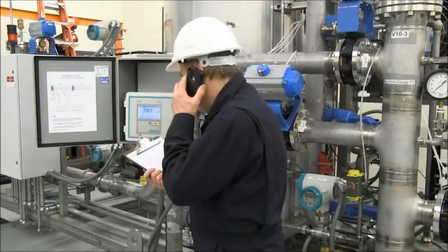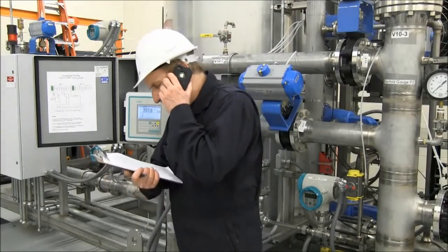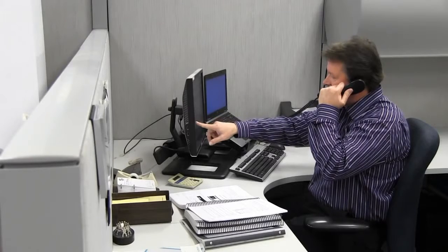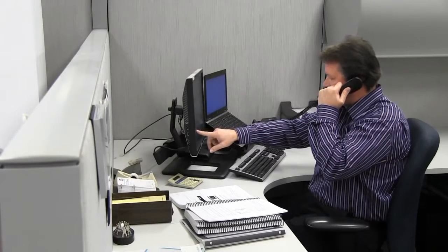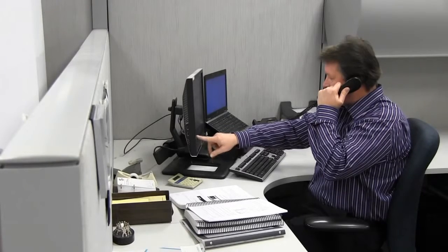Optimization is an exercise of collecting density and viscosity data for your actual liquids and matching them to the liquid table. When the values do not agree, an adjustment to the liquid table is made, which can be thought of as an in situ calibration. Reference data can be acquired from your own lab or from field samples. The values should be for your liquid at base temperature. This data is then compared to the indicated values displayed in the FUH1010 diagnostic menu. This can be done in real time by comparing your data to meter diagnostic values.